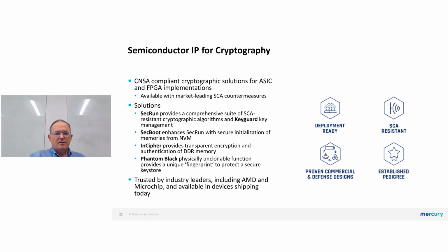SecBoot is an enhancement of SecRun that provides a means to securely initialize memories, random access memories in a system from non-volatile memory. The typical use case for this is boot. However, it can be used at runtime to load any block of data that requires confidentiality and integrity checks with an autonomous function that does not require software to actually perform these operations.